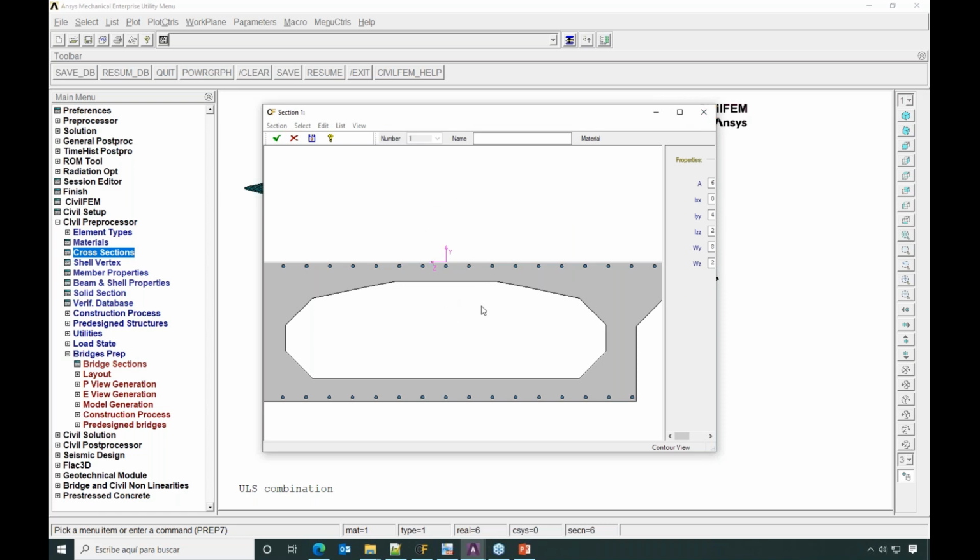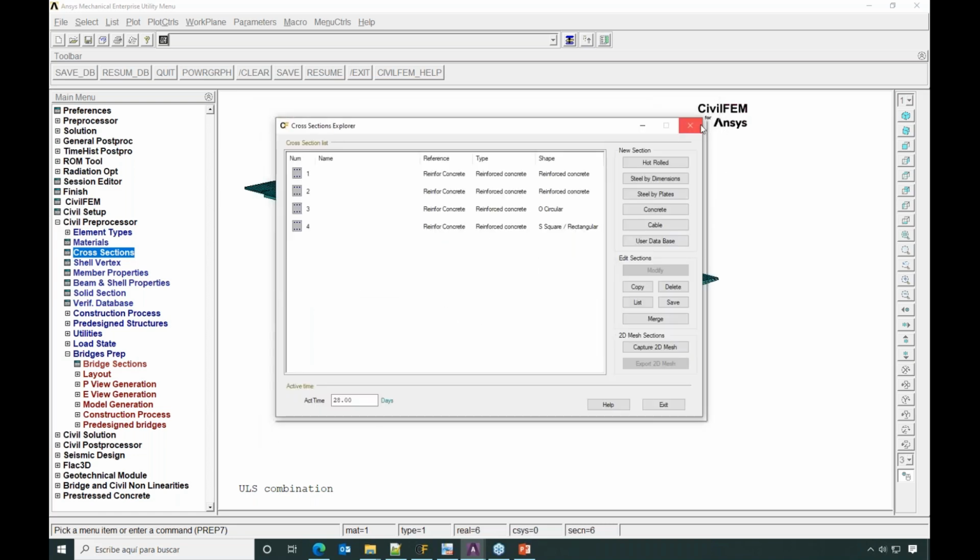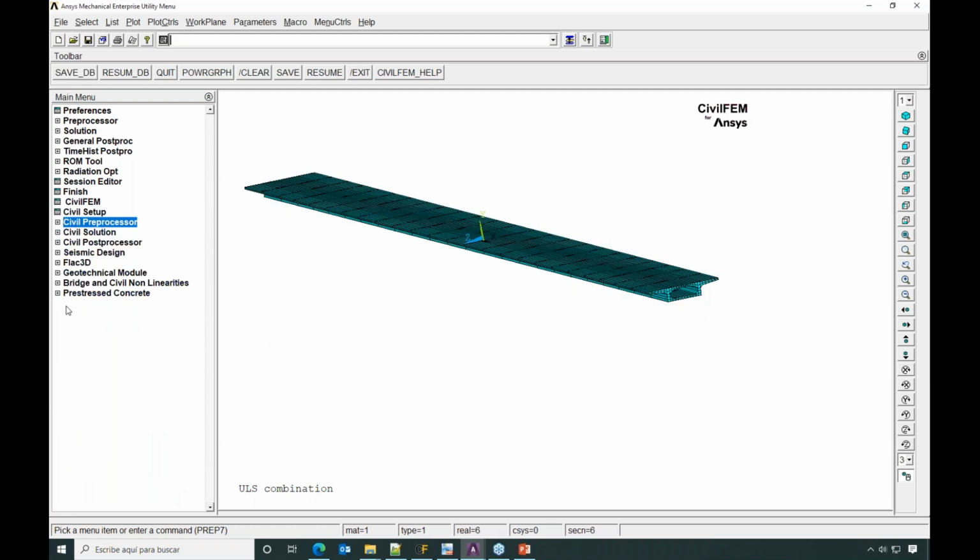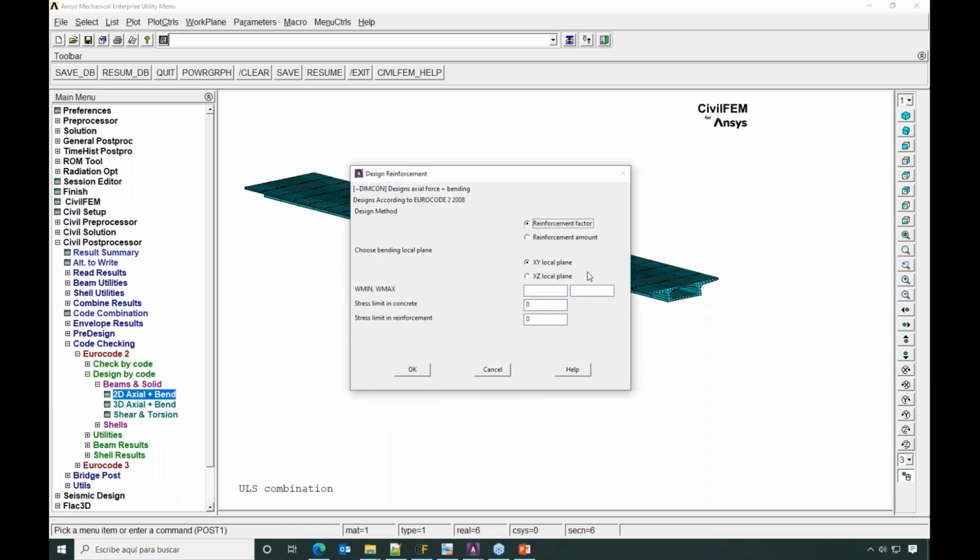So as I don't want the software to go below this limit, what I have to do when designing here is to say that my limit will be 1. That is, I'm keeping this factor for my reinforcement, so I'm not reducing below that limit. So my limit is 1, this is the factor for that. And my upper limit could be, for example, 32 millimeters diameter bar, which is the maximum bar I would like to use. In that case, I should place that maximum limit here.